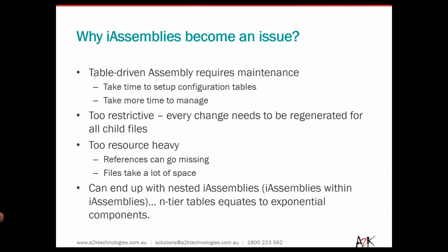So just moving back into the purpose, or the objective of this: why iAssemblies can become an issue. Due to their nature, they're defined by tables. You can appreciate every single table has to have every single row or configuration explicitly set up. This can take time to set up each of your iAssemblies. They also take a lot of time to manage.